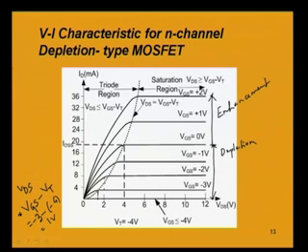So, when VGS is positive, say for example 1 volt, 1 minus minus 4 volt will be VDS, which is equal to positive 5 volt, and so the curves will be bending towards right, because the locus of this drain to source saturation voltage is given by this dotted curve. The equation for this dotted curve is VDS equal to VGS minus VT. That is the value of the drain to source saturation voltage.